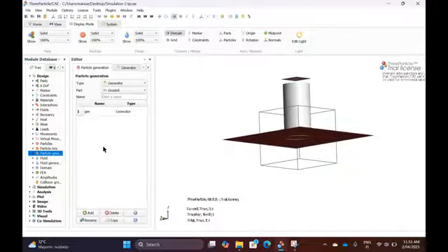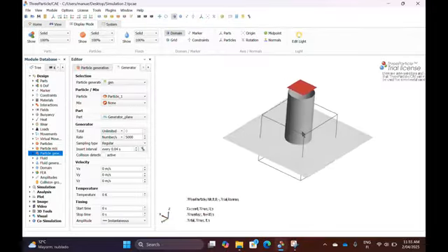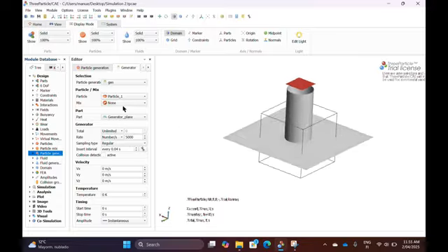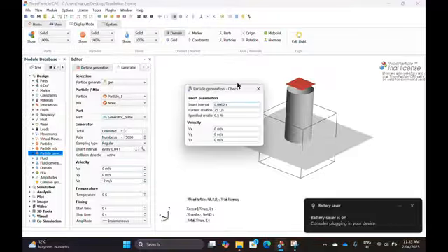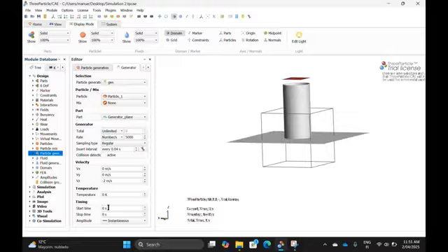If I double click it, I see it again. Now that should be red. The thing above your cylinder should be red. You still go with me? Either your plane or my cylinder should be red. Yeah, the torus should be coming out there. Wasn't so bad before. Let's start with velocity. 2 meters is okay. Downwards. Start time and stop time, very important. Most of the people forget that. And that should be it.